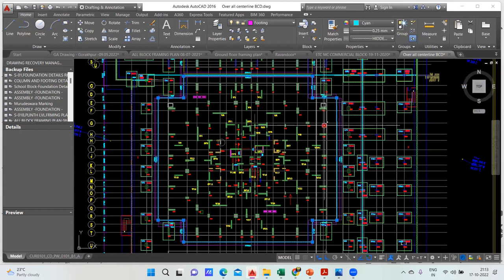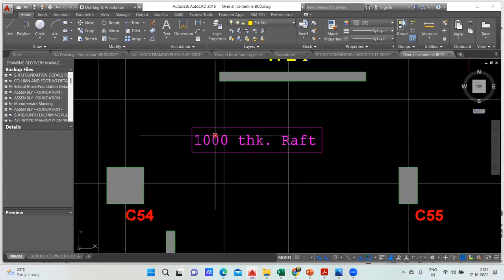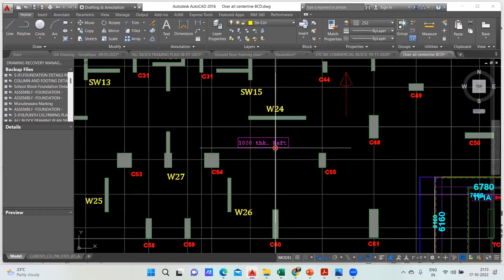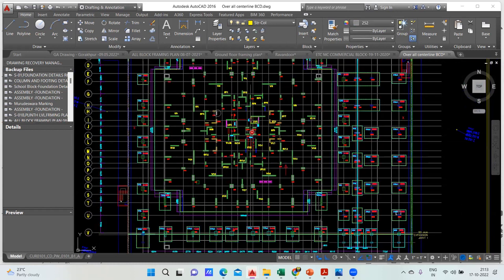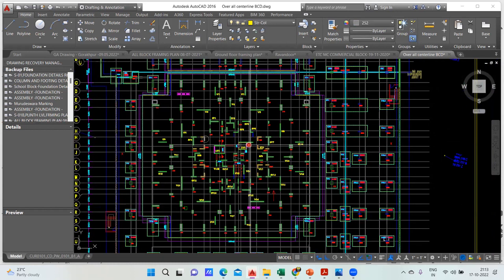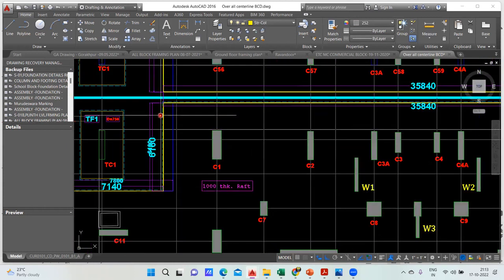The shape is something like this. And now the depth is mentioned here, you can see it. It's written 1000 thick raft, which means 1 meter is the thickness of your raft. The depth of your foundation is 1 meter. Since it's a huge foundation, we'll try to find the concrete quantity. Concrete quantity is pretty simple. Now here, since it's an irregular shape...